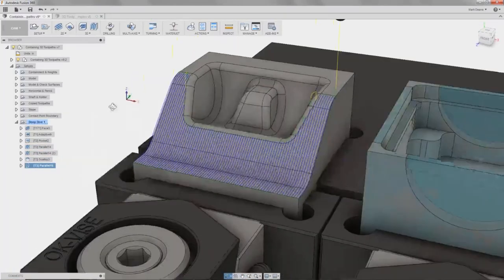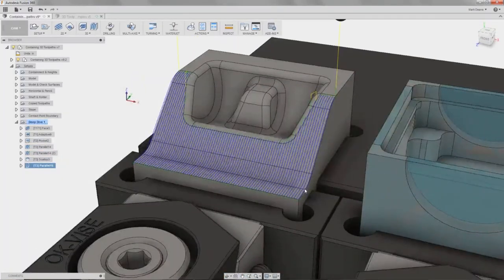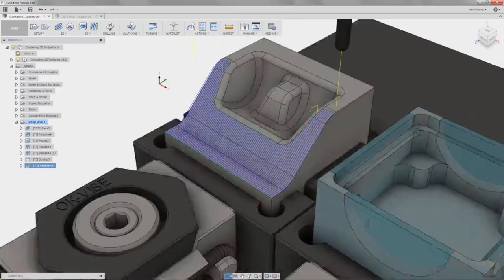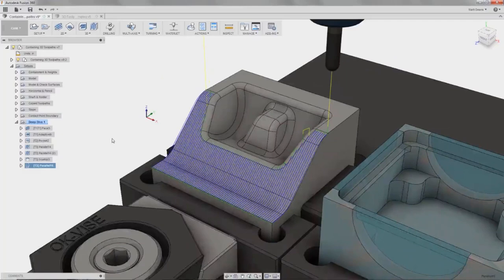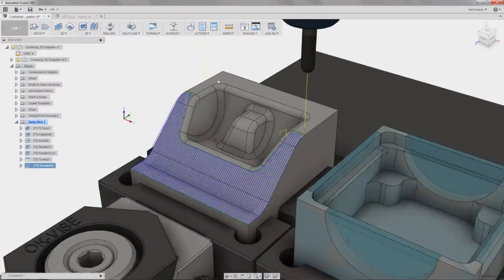So the point of this first part, I know I talked about this first part for a long time for roughing, but the finishing point being made was that containment, or machining boundaries, are a good way to contain toolpaths. So either inside of a machining boundary or between two different machining boundaries. And I can also use heights, like to keep things off this top face. I can use heights to achieve that.